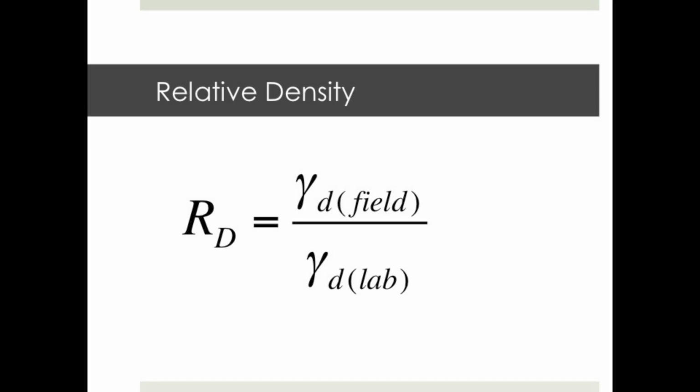To find our relative density or percent compaction, we always compare to our maximum dry density achieved in the lab. If we were to go on a job site and measure the density in the field of a similar material, we could calculate its percent compaction. Also, if we had the in situ moisture content of the field material, we would know whether it is too dry, too wet, or just right.